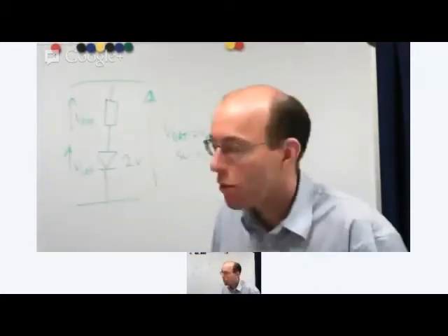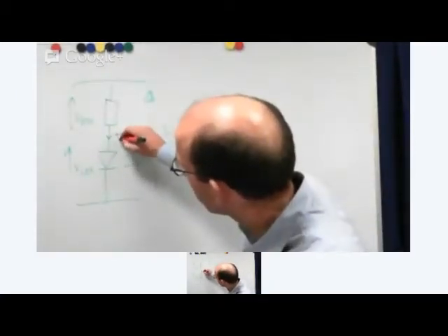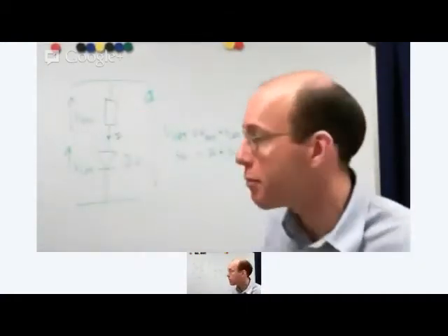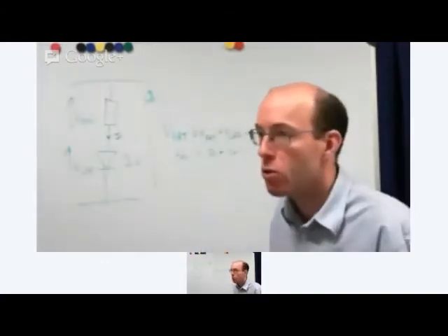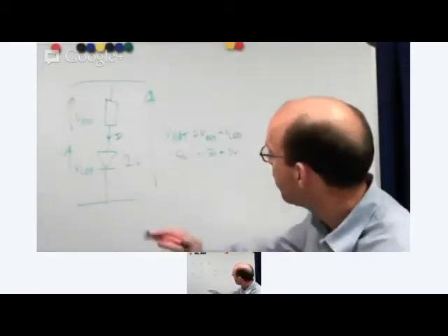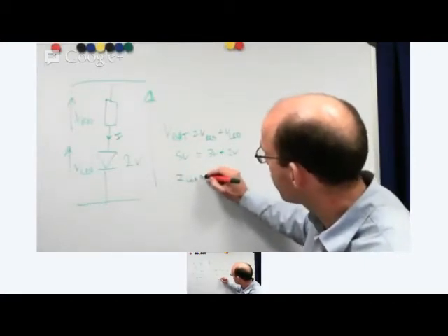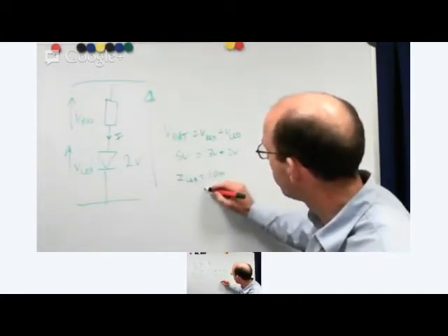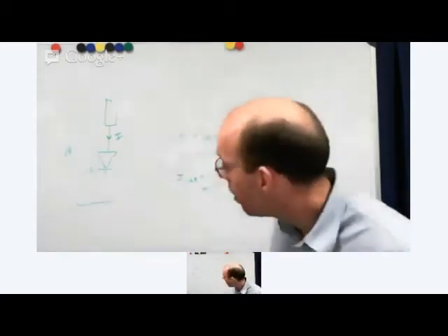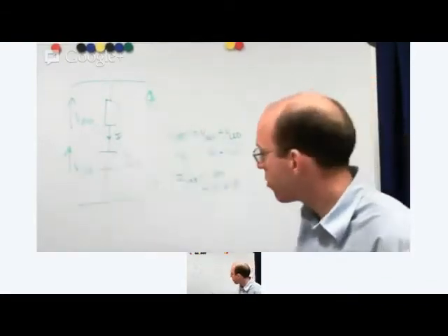What we can then do is apply a little bit of Ohm's law to that, and we need to know how much current I we want, and obviously the current going through the resistor is the same as the current going through the LED. And the data sheet will say typical current might be 10 milliamps, maximum current 20 milliamps for a given LED. So in this case, if we say the current going through the LED is equal to 10 milliamps, or 0.01 of an amp, which is obviously the same thing, then we can apply Ohm's law to this, and we can work out what the value of the resistor wants to be.